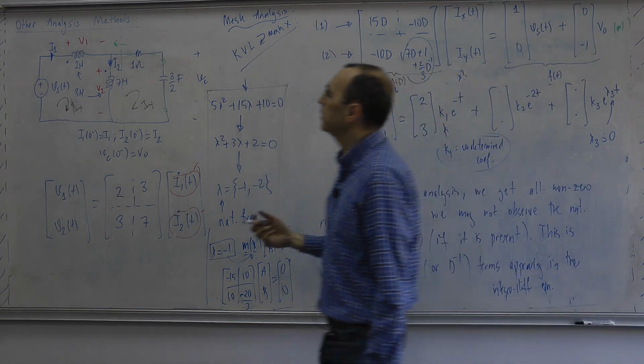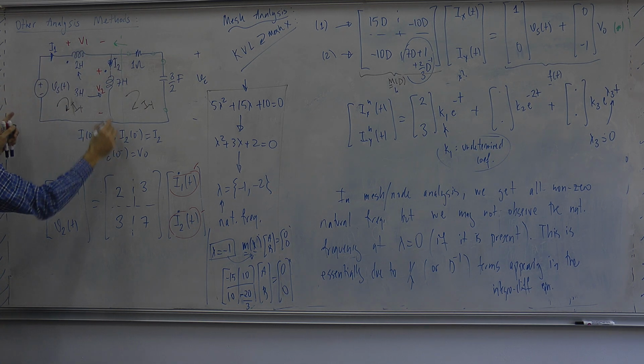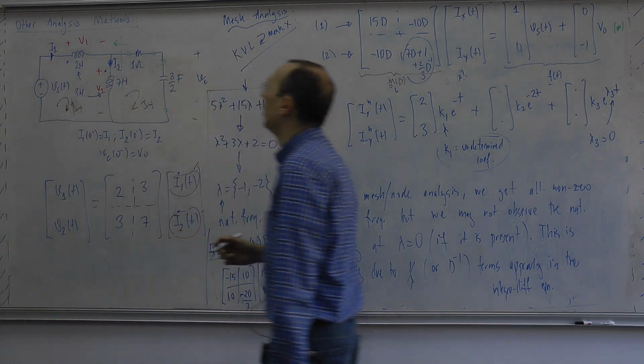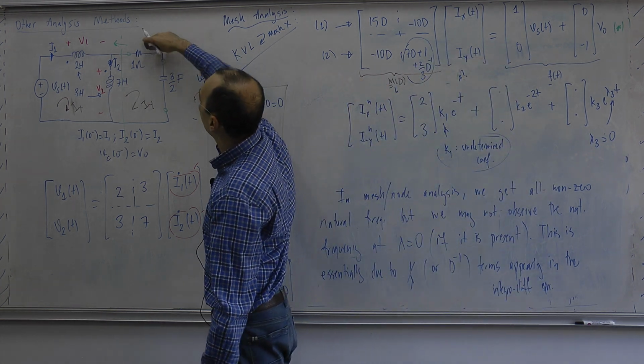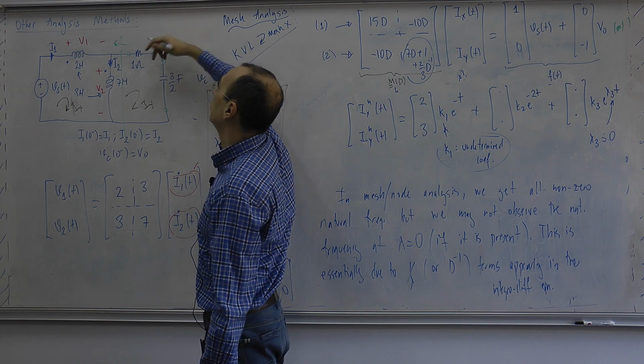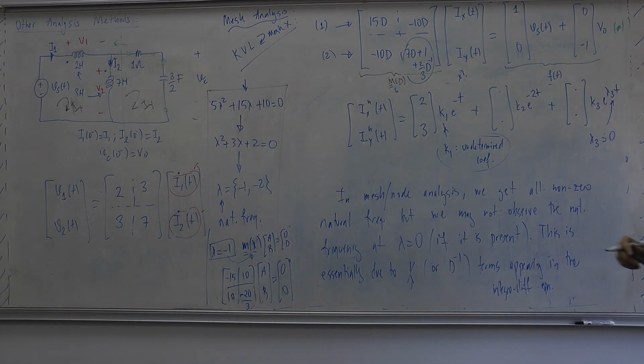They can never understand whether there is a mutual inductor or a single inductor in this equivalent part on the left-hand side. So for the sake of these two, they are sensing something like a second order circuit. There is an inductor and a capacitor, so it's a second order circuit.